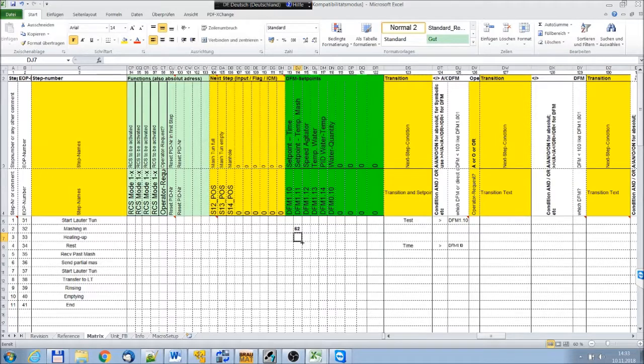And the next one, heating up, is going to 66 degrees, and then in the rest time it remains at 66 degrees. Okay, that's the technology. Now there is something. In reality, you want to have the steam valve switched off when the temperature is okay.